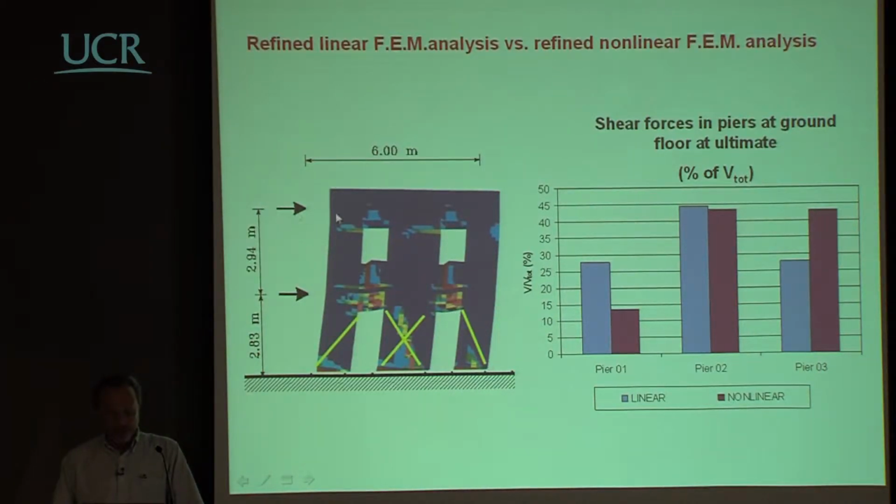So when you're pushing in this direction, you will be opening maybe this and this, but you will not be opening the other crack, the one that should come here, because in this wall you have a much lower shear, because this wall has a lower compression force. When you push in the other direction, you will be opening this one and this one. So in the outer wall of a combined masonry structure, it is very likely that you are going to see cracks that are pointing towards the toe of the wall in the external direction.